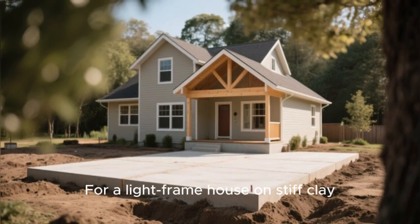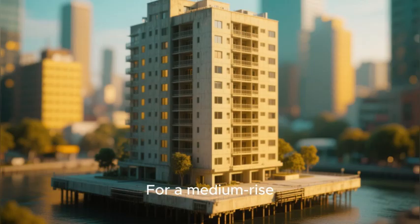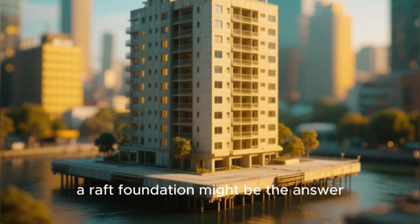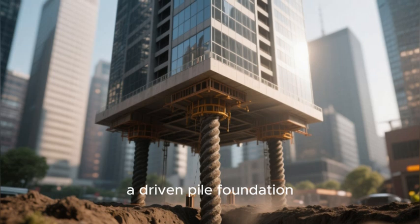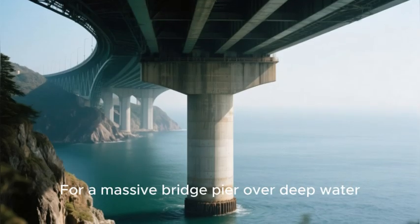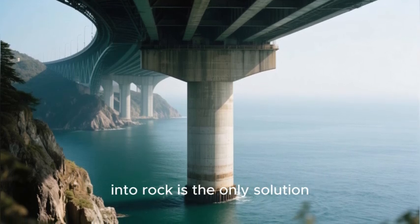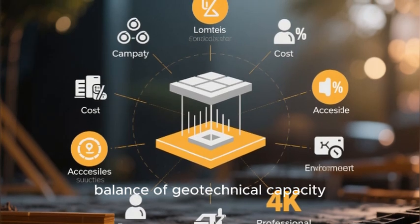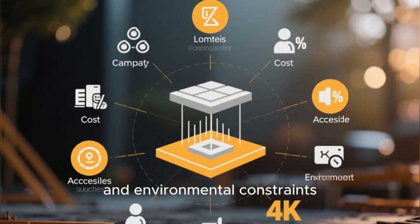For a light frame house on stiff clay, a simple slab-on-grade or strip footing is perfect. For a medium-rise building on variable soil, a raft foundation might be the answer. For a skyscraper on soft soil over dense sand, a driven pile foundation transferring load via friction is ideal. For a massive bridge pier over deep water, a large diameter drilled shaft socketed into rock is the only solution. The choice is a complex balance of geotechnical capacity, structural loads, cost, construction accessibility, and environmental constraints.